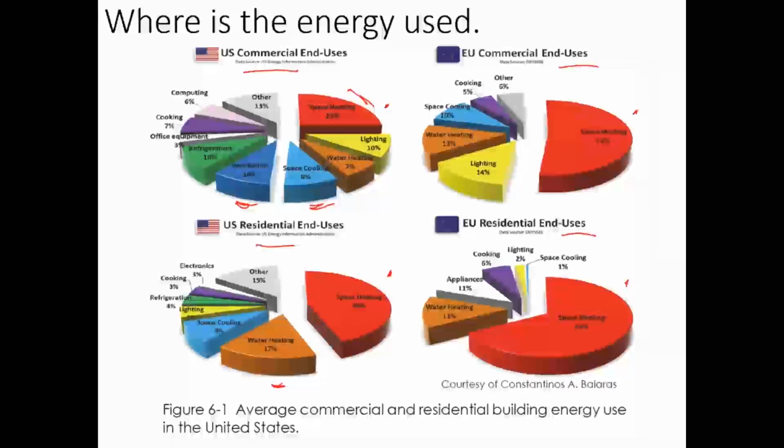But again, it goes back to the building as a system. You have to think about how things are going to change, what's affected when you make these big changes. Incandescent lights are like little radiators. They give off a lot of heat, right? So in the winter, that adds to your heating capacity, and it can be a substantial amount depending on how you design the lighting in your building.